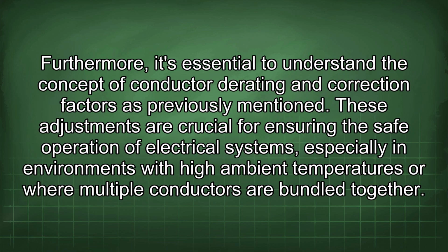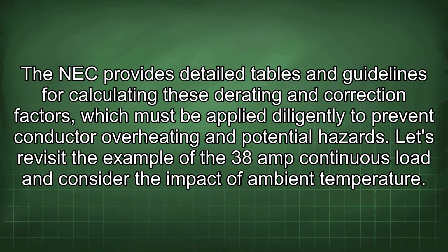Furthermore, it's essential to understand the concept of conductor derating and correction factors as previously mentioned. These adjustments are crucial for ensuring the safe operation of electrical systems, especially in environments with high ambient temperatures or where multiple conductors are bundled together. The NEC provides detailed tables and guidelines for calculating these derating and correction factors, which must be applied diligently to prevent conductor overheating and potential hazards.